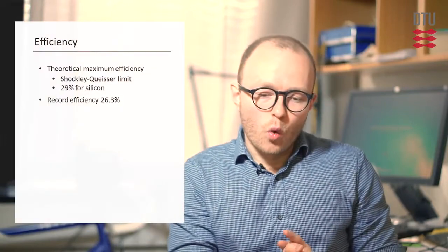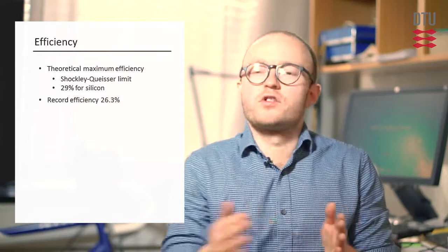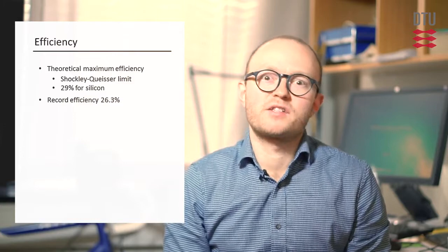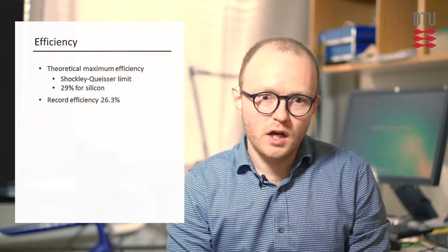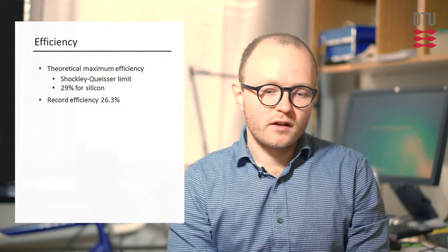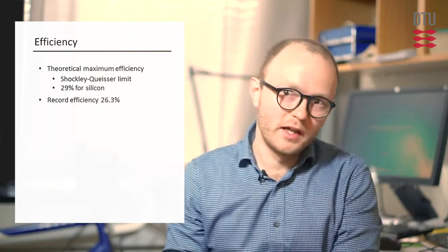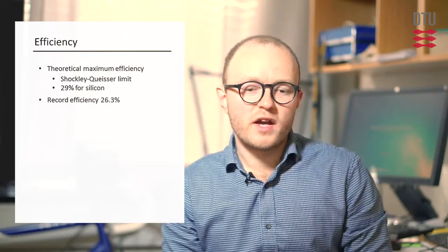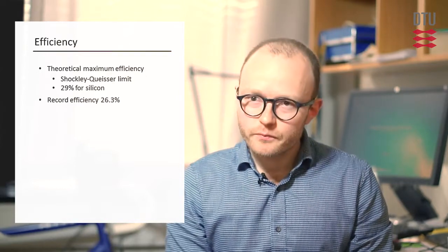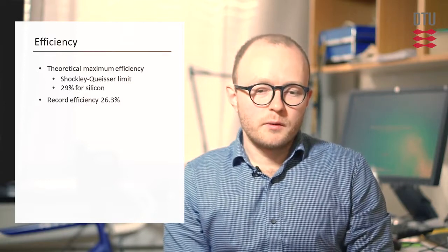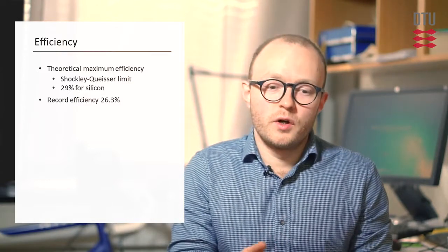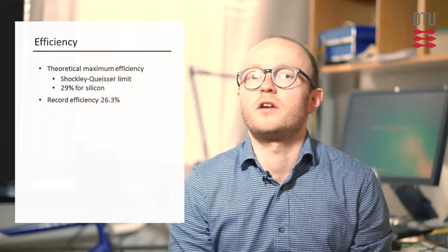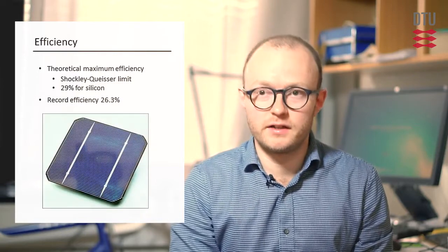So if we look at what's been done and what's left to achieve the theoretically maximum possible efficiency of silicon solar cells, what's left is both some optical and some electrical losses that are still present. Even the record solar cells today still have some reflection. Even the best monocrystalline cells, if you measure the reflectance, still reflect a lot of the blue and ultraviolet light.